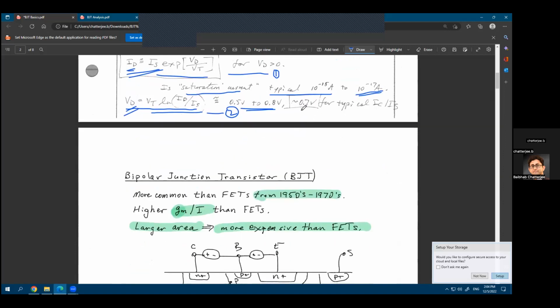So usually you'll see in books that the voltage drop across the diode is assumed to be 0.7 volts. But you need to keep in mind that that's not strictly true. It can vary depending on the amount of current flowing through the diode, but it is okay to approximate it to be a certain value around 0.7 volts, as we have found from the numbers.